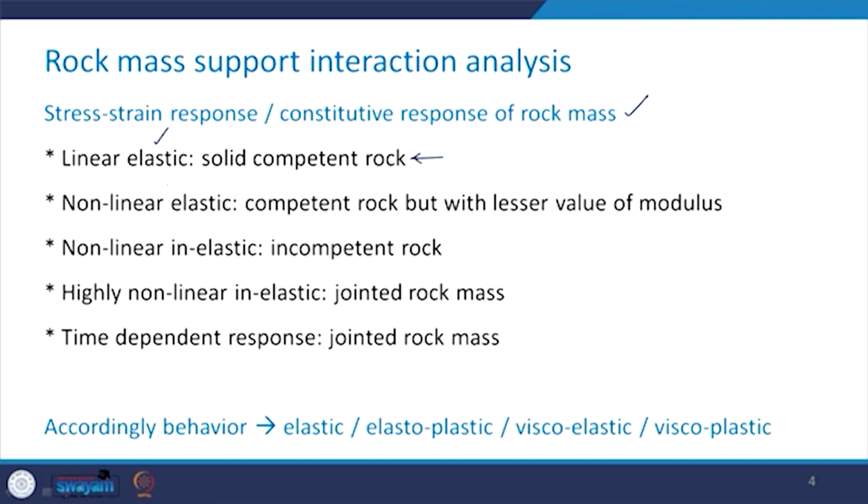It can be nonlinear elastic in case of competent rock, but with a lesser value of the modulus. It can be nonlinear inelastic in case of incompetent rock, highly nonlinear inelastic in case of jointed rock mass, and then you can have a time dependent response also in case of jointed rock mass.